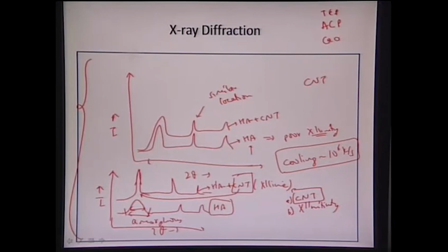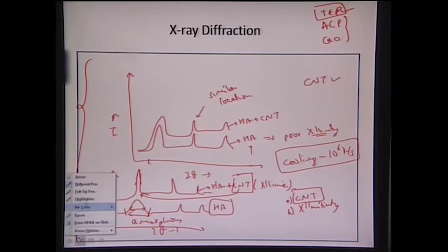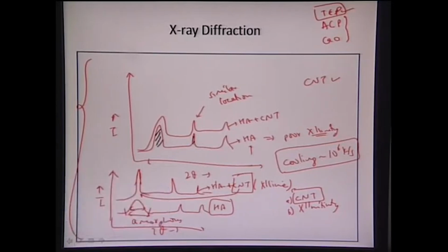But what we are seeing in this particular spectrum is no presence of any other secondary peaks. But there can also be certain TCP peaks because of the rapid kinetics involved in plasma spraying. So we can also observe some TCP peaks that will induce some amorphous nature in the coatings. Ideally, the crystallinity which is being induced can be calculated by the area under the peaks. The area under this particular peak can provide us the overall content, or the crystalline nature, of this particular peak.